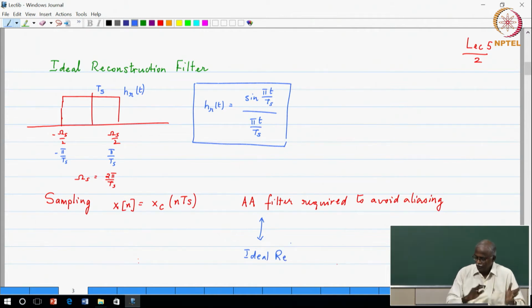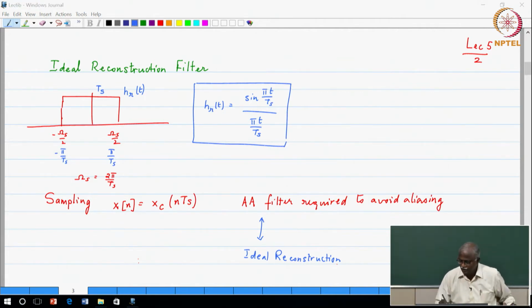So, both the process of sampling and reconstruction again show similar things, in terms of the requirements on the ideal reconstruction filter. Okay. So, keep in mind that that's for a particular sampling frequency. Anti-aliasing and reconstruction require filters of similar properties. Okay. I thought you may have already noticed it, but I thought I should mention because they are actually identical for a given omega s.